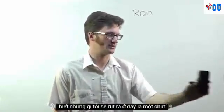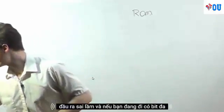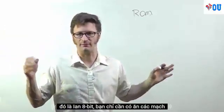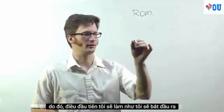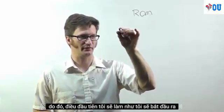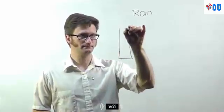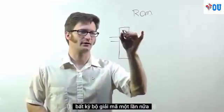Now what I'm going to draw here is a 1-bit output ROM. And if you were going to have multi-bits, let's say an 8-bit, you would just have to have 8 of these circuits. So the first thing I'm going to do is start out with a decoder again.